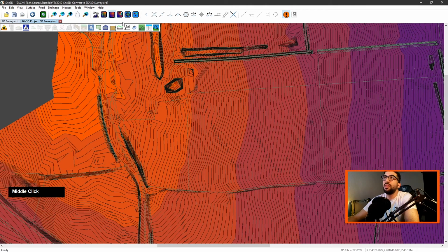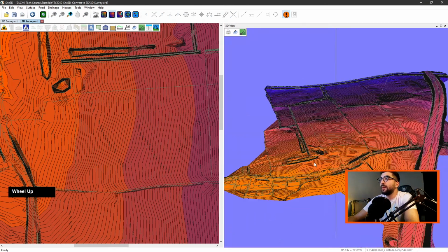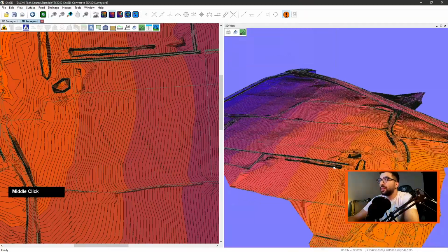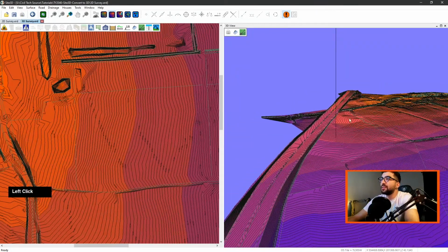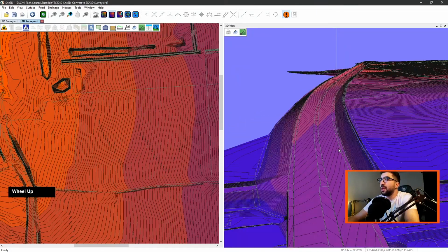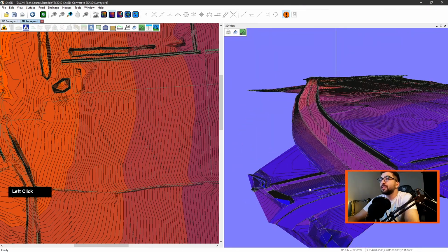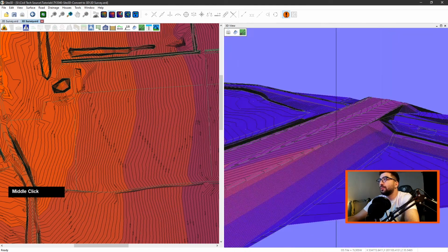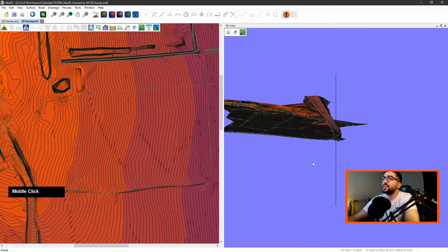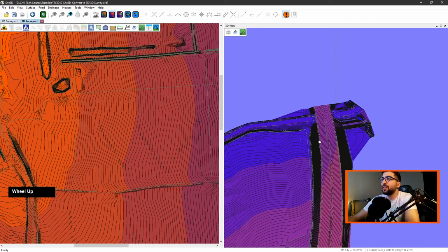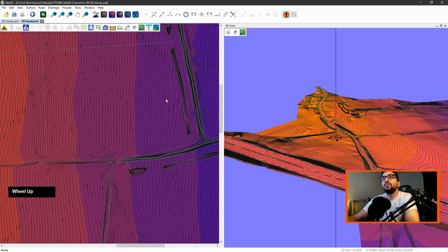Now, if I want to view the 3D model, all I have to do is display 3D view, and it picks up. So basically, as soon as you open your drawing, Site3D actually creates a 3D model and you can view it because it picks up that it has 3D information. As you can see here, it picks up the road and everything. So I think the default settings for snapping, it picks them up. So now you can download this file from the Site3D sample data. It's the one that you can try, and you can follow this tutorial along. That's all you need to know basically to do your topographical survey.